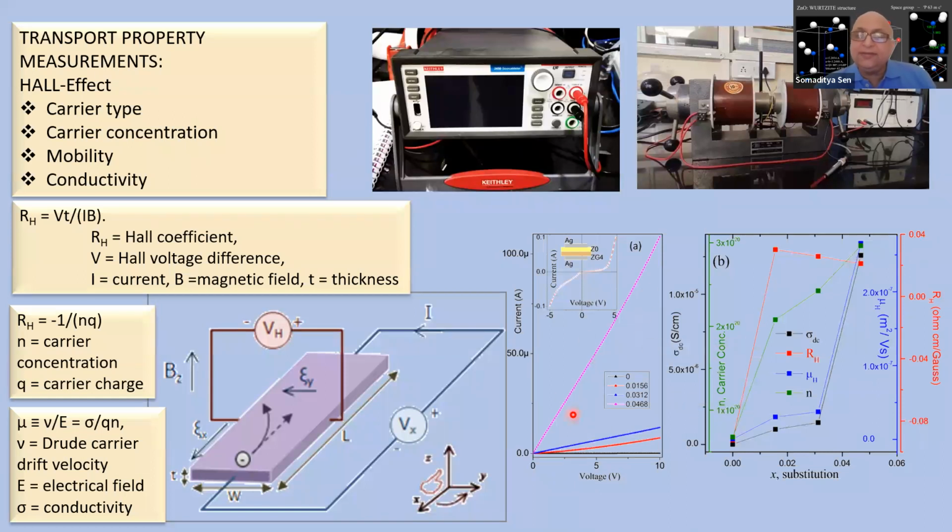Now, such a thing can be verified by sandwiching two N-type and P-type materials. This is one of the classical examples done in our lab, actually. We could find that zinc oxide has a negative Hall coefficient, and the gallium doped ones have a positive Hall coefficient. They were sandwiched together, and we found a perfect PN junction type behavior in this material.